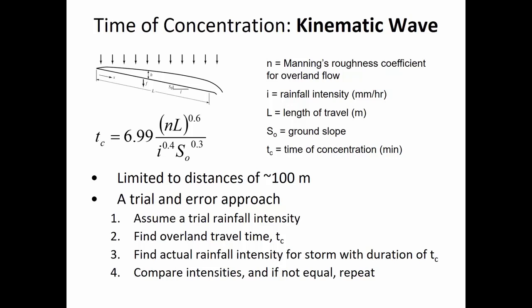Why? It's going to have a higher speed. It will run off more quickly. And the same thing is true of rainfall intensity. It's the same trend we were talking about earlier when we were looking at the C values. If you have a high rainfall intensity, then that's going to decrease the time of concentration because the water's moving quickly.